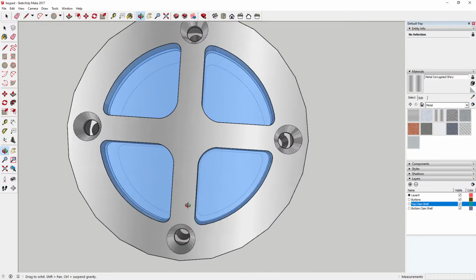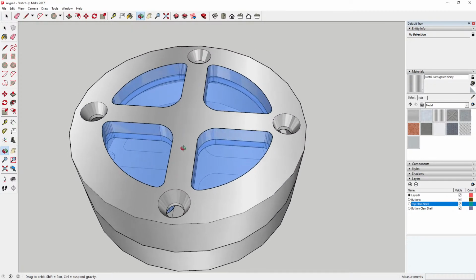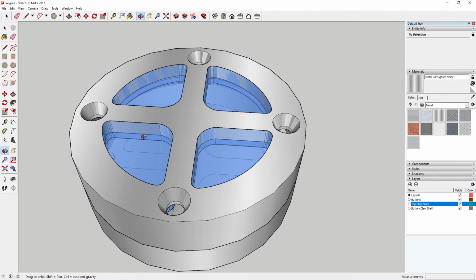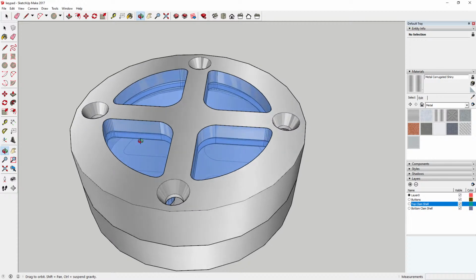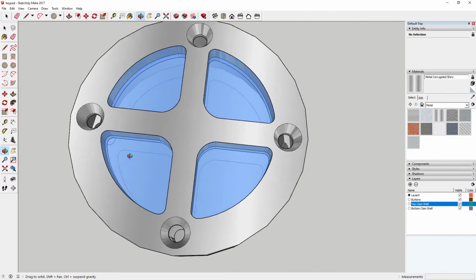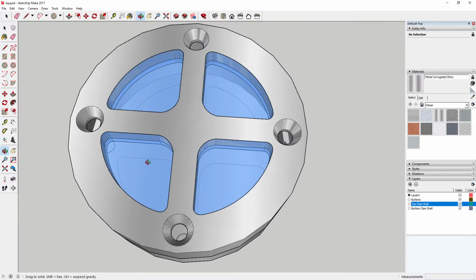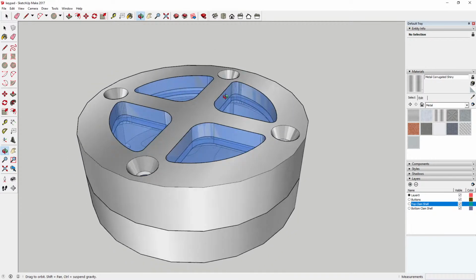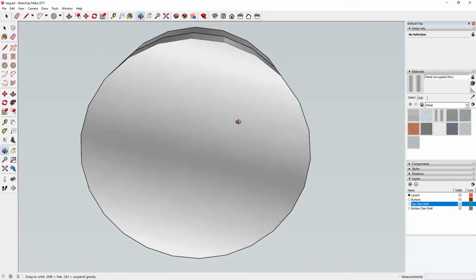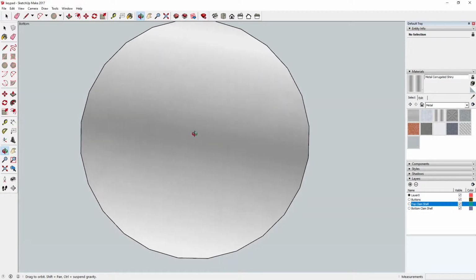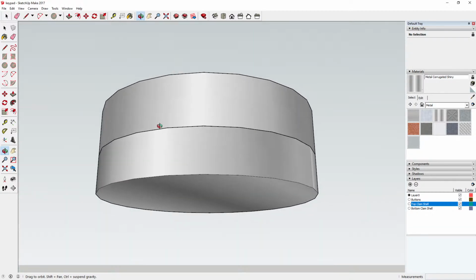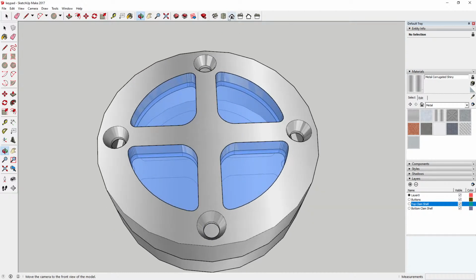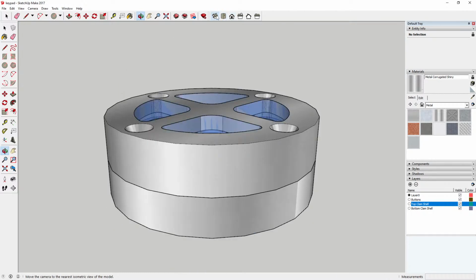So they've got to work out the PCB, the push button down onto a physical stop, so the plastic push doesn't break the button if it's over pressed. And you've got to add the circuit for the illumination and the contact and IC. And then we're going to need a hole in the back for cable and fixings, so we've got that to do.